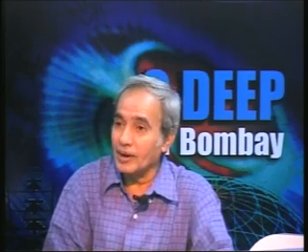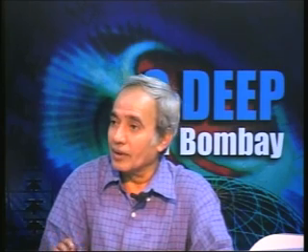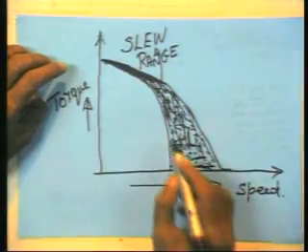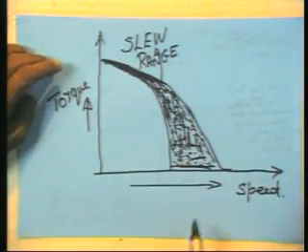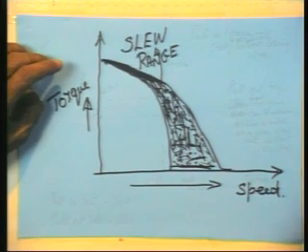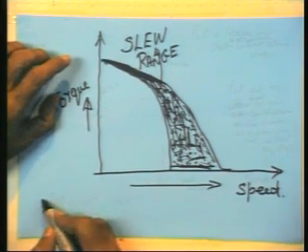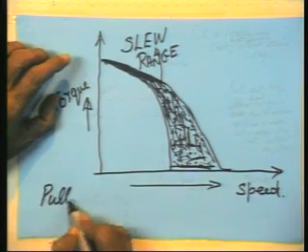Okay, when your operating speeds enter the slew range, don't try to accelerate or decelerate. This is something I have seen novice students do: they do not look at the torque-speed curve in the slew range. So there is what is known as a pull-in torque.